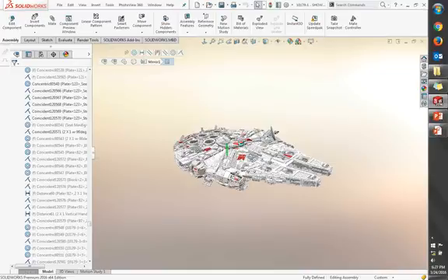So I sat there and thought about it. I'm like, you know what? I fixed all these components. I'm in the whole fixed component thing. This is never going to work out. The cool thing is if you have a component that's fixed and it has mates that are suppressed because it's fixed, when you right-click and float the part, it also unsuppresses the mates automatically for you.